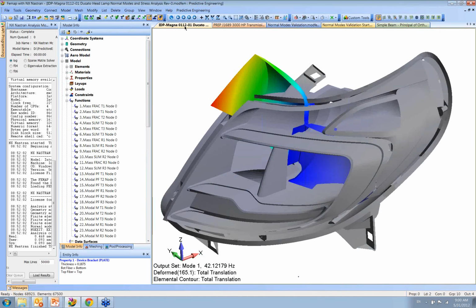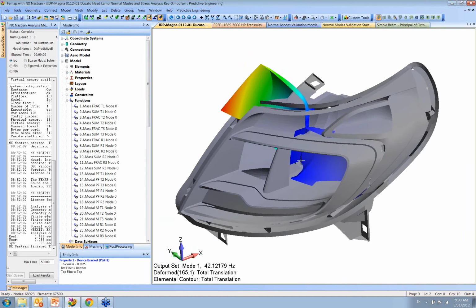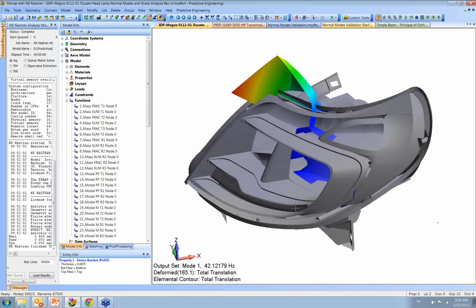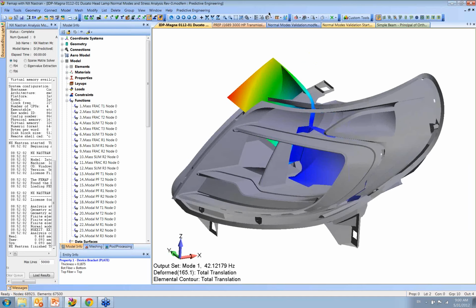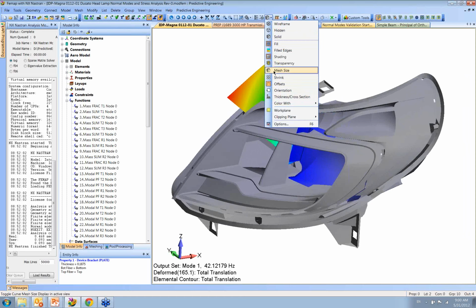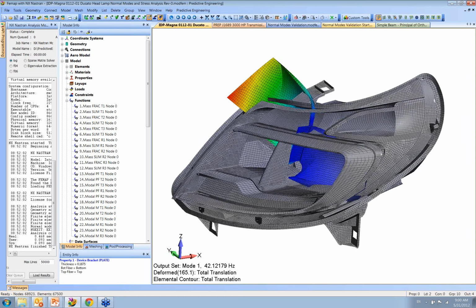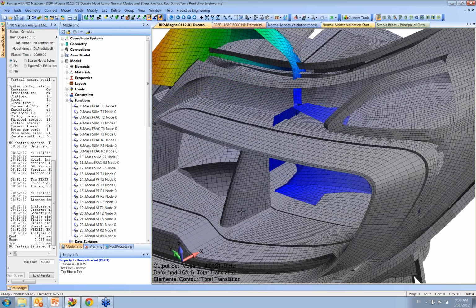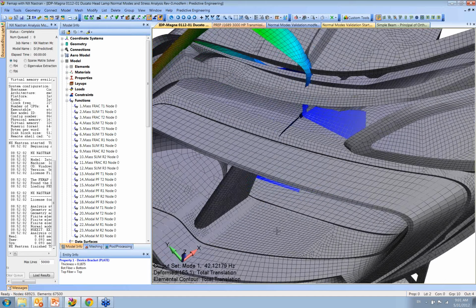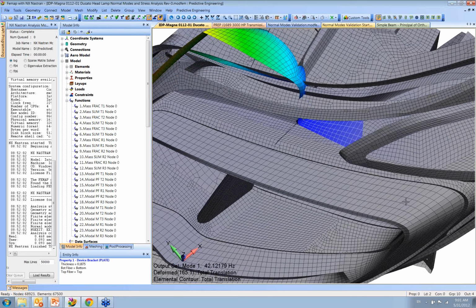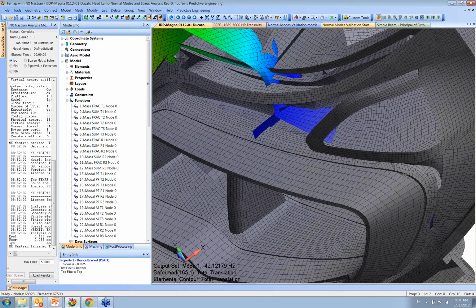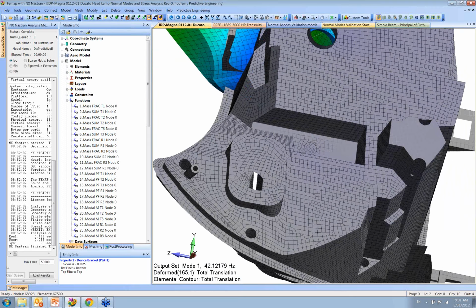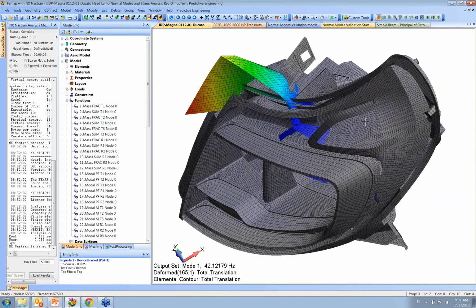There it is. Ducato. We got involved with doing a bunch of headlight assemblies, and it's interesting. They're really complex. So this is for Fiat, and there's the mesh outline. Very careful meshing, using the whole skill set of getting meshes lined up carefully. Nothing's perfect, but a lot of this stuff just goes along for the ride. And anything important, like this base pattern in the back, you're quite careful in meshing.